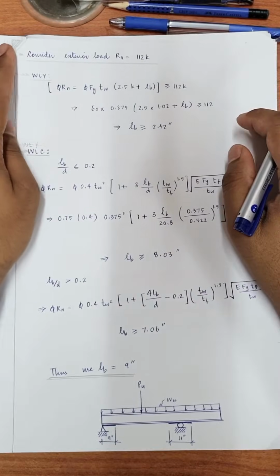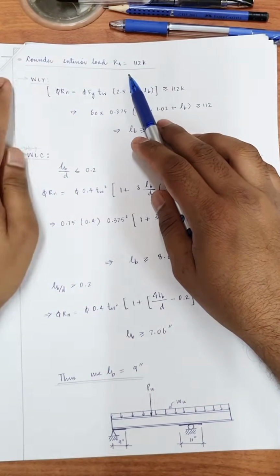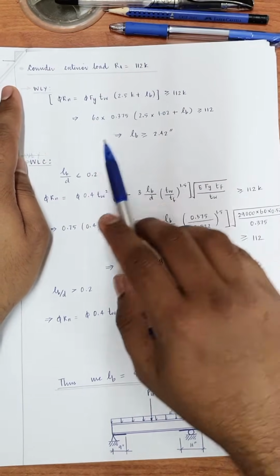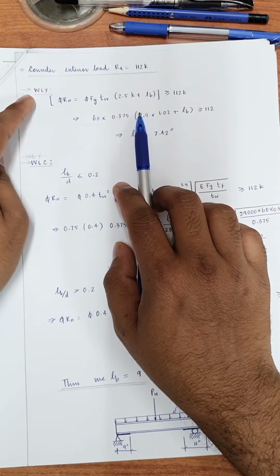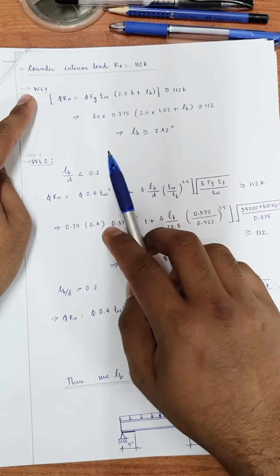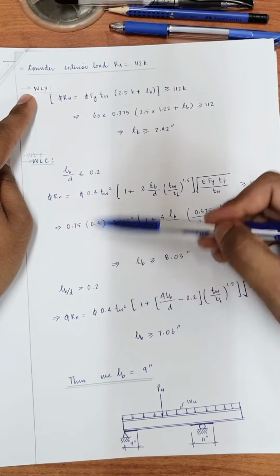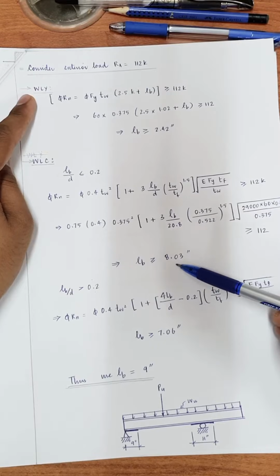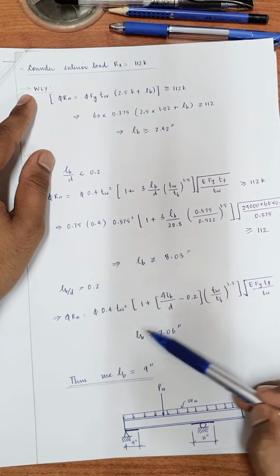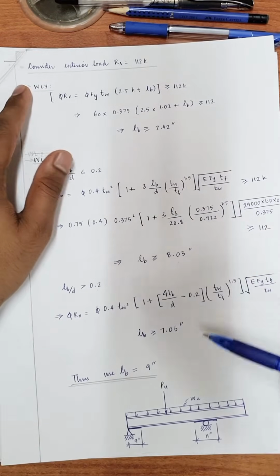Now the next concentrated load that we need to check is RA equals 112 kips. When you check the web local yielding because of this load, we get a value of LB as 2.42. And again, for web local crippling, you have to check both criteria, and your LB value is 8 when you check this criterion, and when you check this criterion, LB over D greater than 0.2, you get LB as 7 inch. You take the larger of the two and round it off to the next whole number,